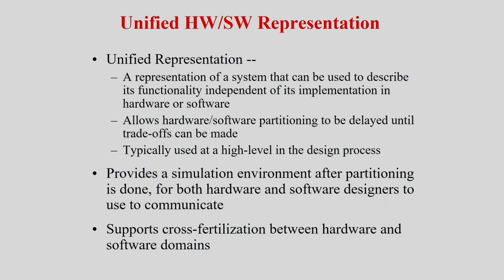The problem number 1 is very simple. I have a co-environment. So whatever hardware and software version I have, I will download it, simulate and see whether there are any bugs or not. So bugs will be found very early. I can also find out that at every stage the design is correct or not, because I have an entire working version in software. So I can see whether the design intent is met. Bugs are caught earlier. Easy design trade-off: if I find this one is good in software, I can put it in hardware and vice versa.